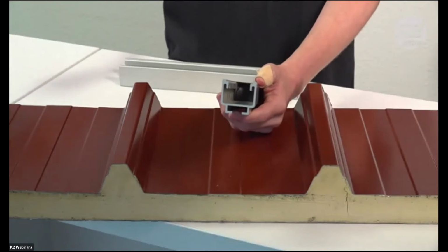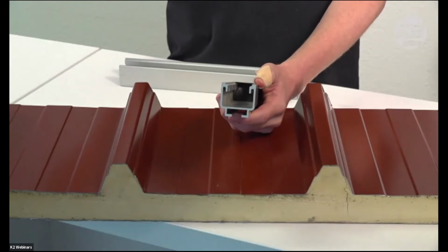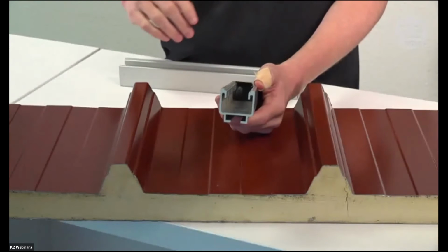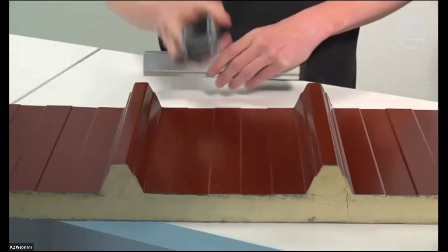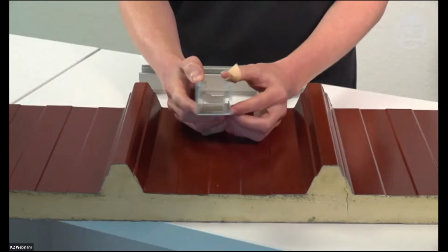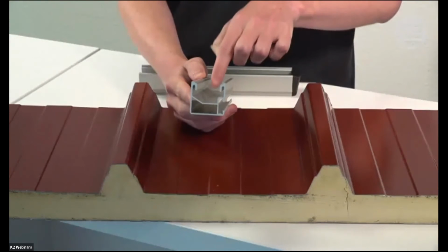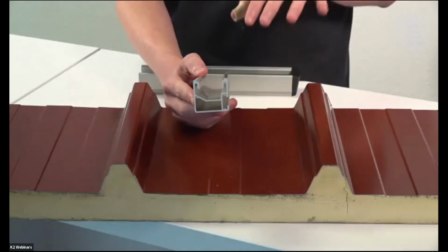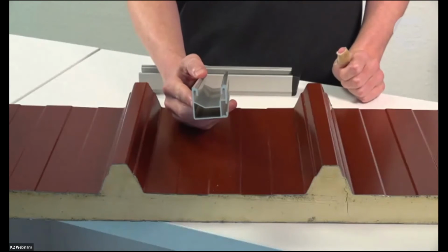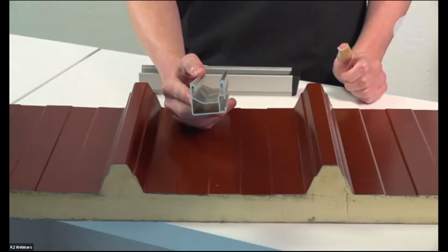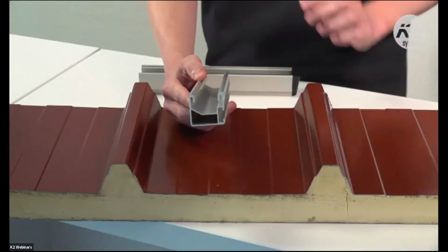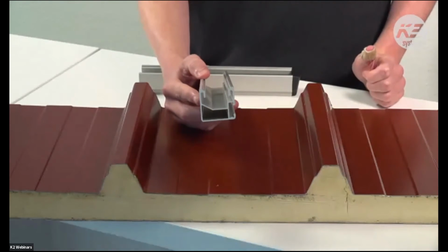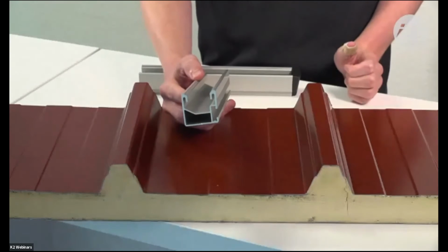So if the cost of your project is sensitive to labor costs, perhaps it might not be as suitable as the single rail, because the single rail is a little bit easier to install. So you can see here we have the same channel on top, and the fixation is from the side. So this is suitable for the solar fasteners and the hanger bolts for today, and also our many other systems we have on different sort of roofs. So our tile roofs and our seam clamp roofs, we also use these rails.